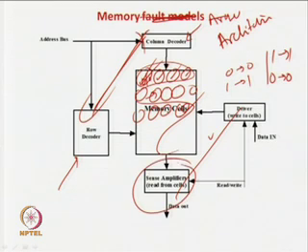Similarly, for sense amplifiers, you write some data and you access some data. If you are writing proper data and getting proper data back, that means the sense amplifier is correct if you are reading the proper data, and if you are able to write it properly, then you are testing the driver. So, explicitly you need not test all these parts.